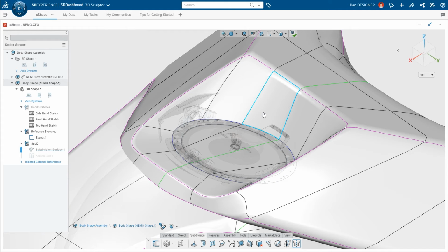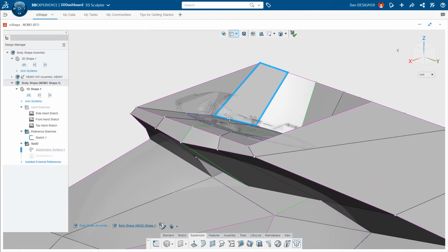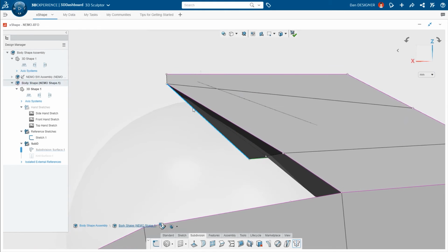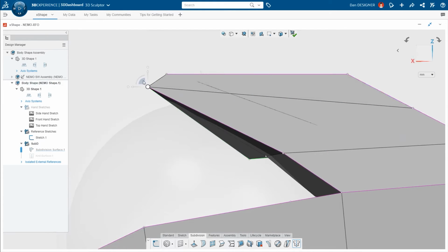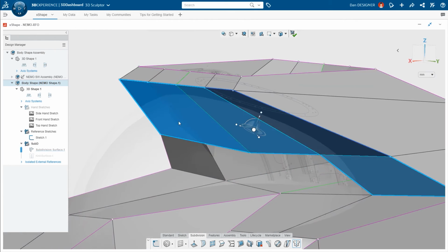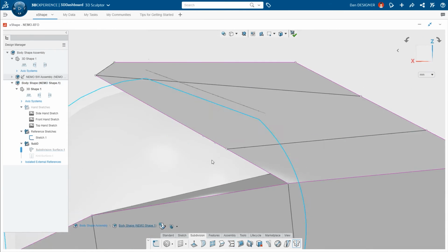Just like style splines in SOLIDWORKS help to parametrically control splines, the cage view in X-shape reveals the underlying constraints driving the curved surfaces, making it apparent when edges are out of alignment. After selecting the vertices in sequence, Dan can easily align them to each other. The side view reveals that the front faces of the hood are also out of alignment. Once selected, they can be made coincident to each other from the context toolbar, just like mates in SOLIDWORKS.